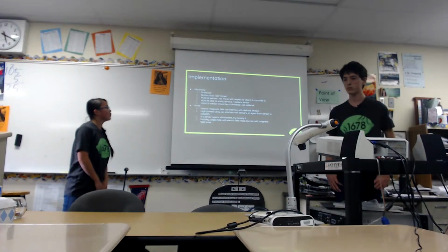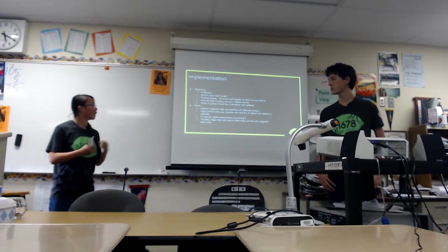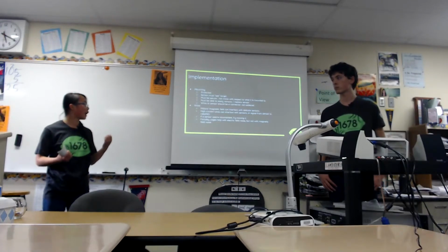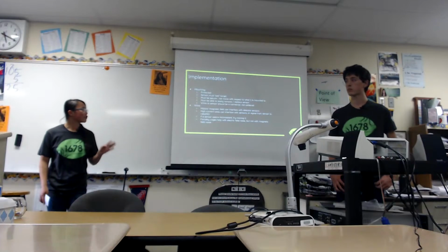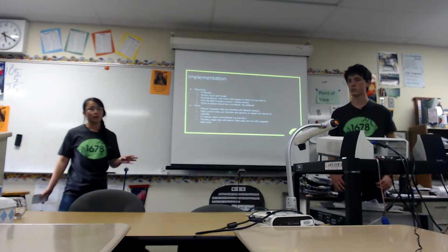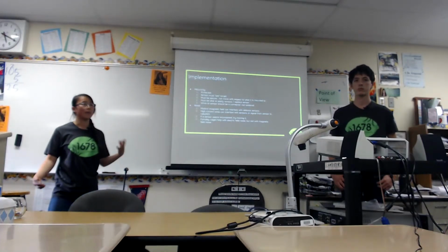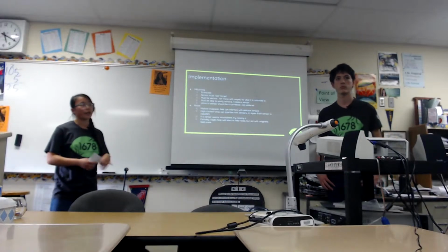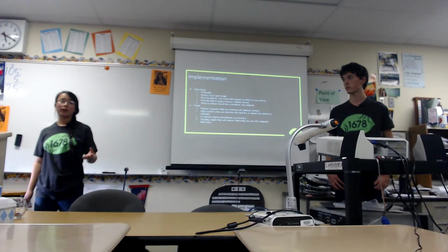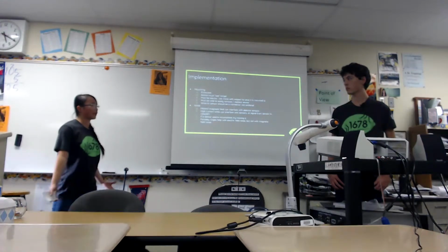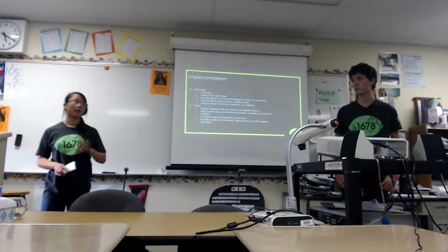And the wires should have a connector, not solder, so you can actually change it out if you need to replace it. Also, make sure there's no magnetic or electric noise which can interfere with it. That would come from a motor or from high current wires. You can use Faraday cages to help with the electric noise, but that does not help with the magnetic. So make sure that you place it away from a motor.